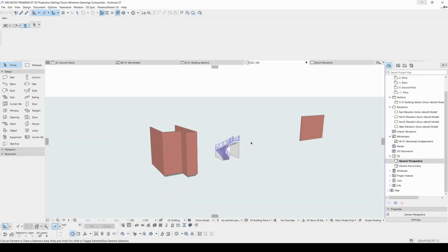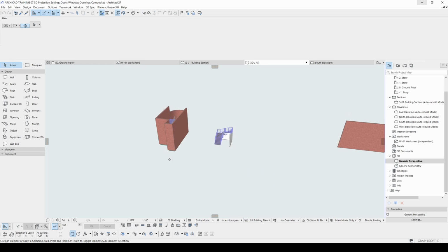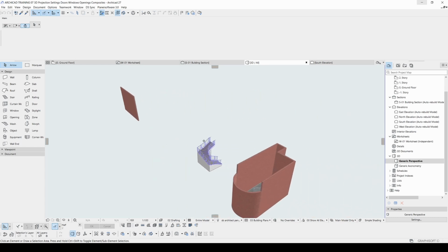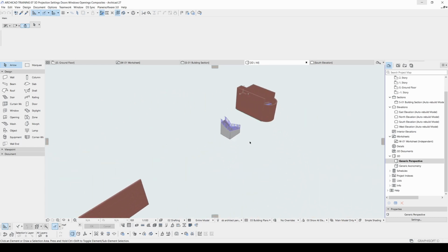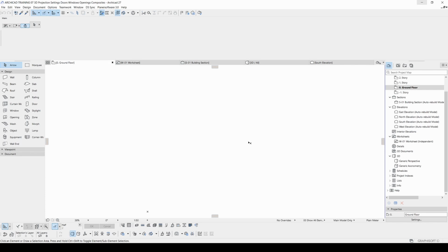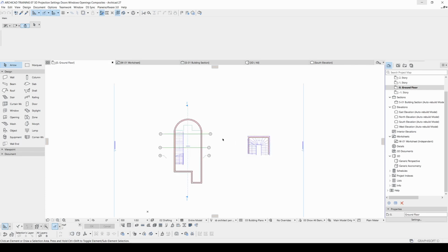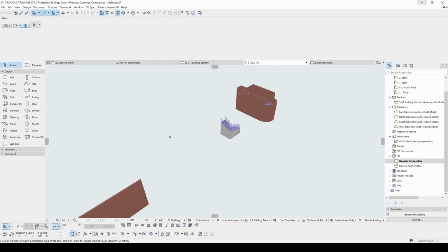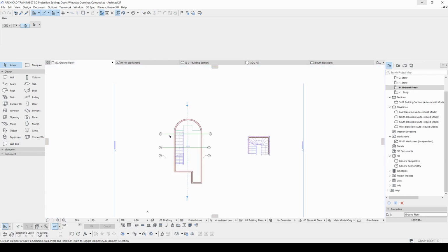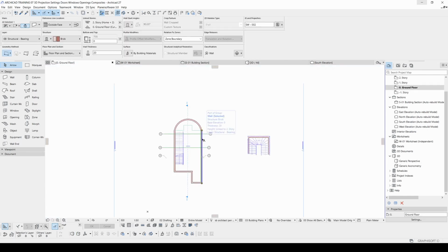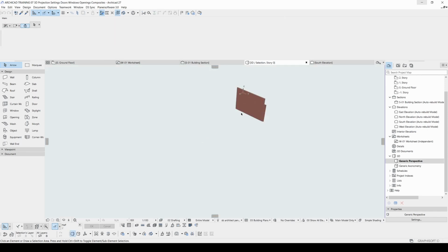button. And you can find your 3D elements which you created in the floor plan. And if you hit F2, you will go back immediately to ground floor. But if you hit the F5, you will see the same. But there's a difference. If you select something on floor plan, if you hit F5, you will only see the selected element in your 3D window.